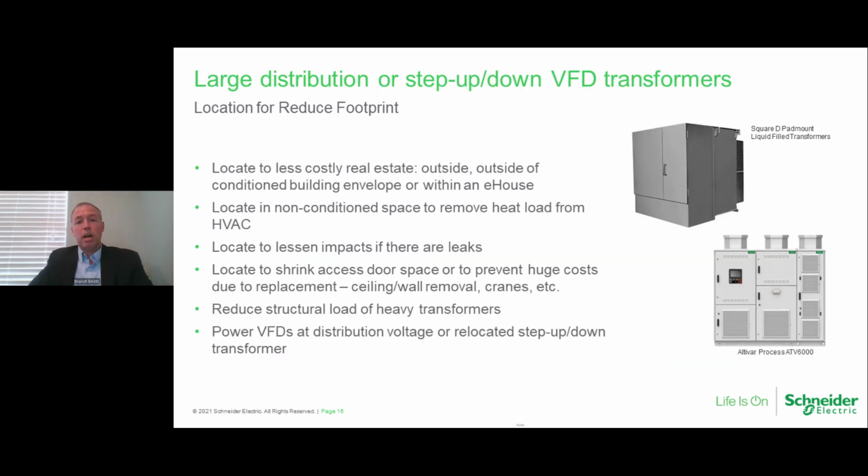We also like to move a lot of our large equipment outdoors, especially when we're talking about transformers. Once again, air conditioning loads, that's a major reason. You don't have as many requirements to support the equipment itself. And when you're talking about transformers, especially liquid filled transformers, removing the containment requirements from the building and putting it outdoors can have a big impact on your project.